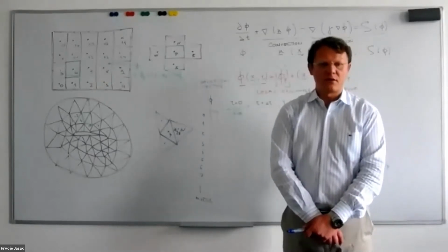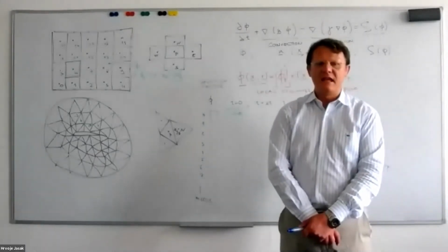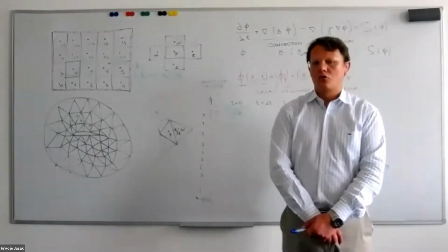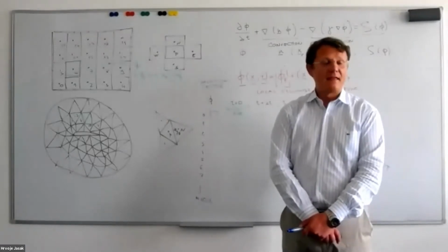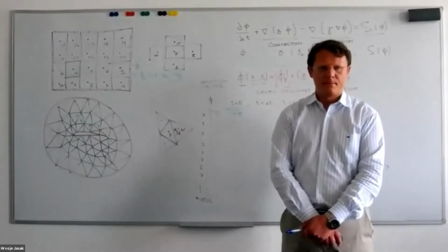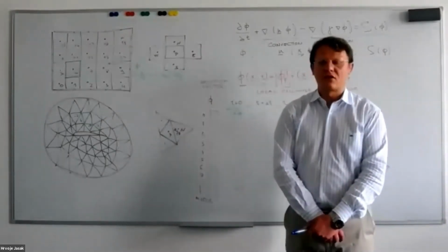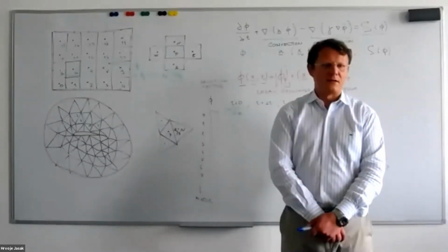The definition of the centroid says that the volume integral of x minus xp dV is equal to a zero vector. And that definition applies to an arbitrary shape. Apart from that, I need to be able to describe the individual faces.